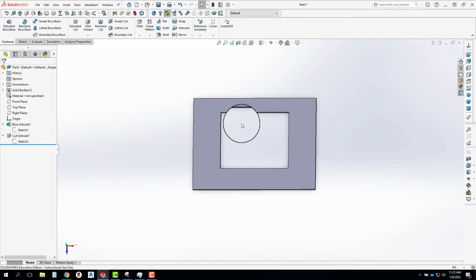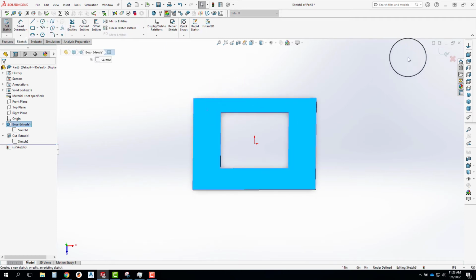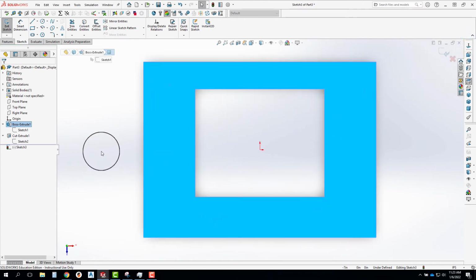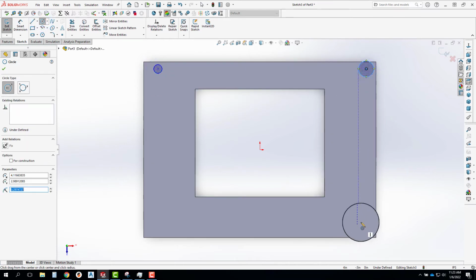Okay, so we've used the vertical and the horizontal. Let's start looking at our screw holes that we need to add into it, and that'll give us some more relations that are useful. So I want to add some screw holes. And you can see as I'm drawing here, it's trying to infer relations, and that's fine, but I'm just throwing them out here kind of randomly in size and space, and then I will use relations to create symmetry about it. Anytime you're doing bolt holes, often it's in a pattern that you want to have symmetric. So we're going to look at some relations that help us with that.